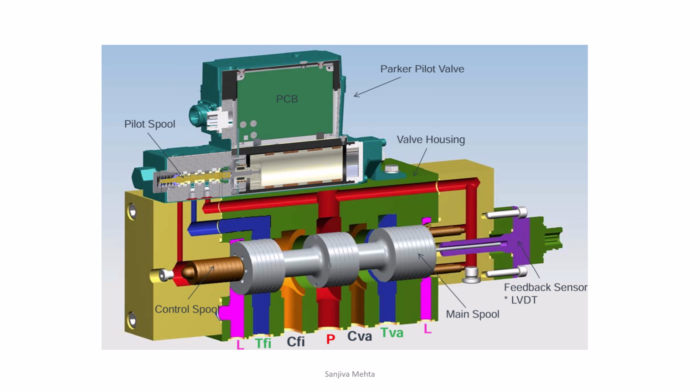This is your FIVA valve. These are various channels. This is the valve actuator. This is for the injection side. This is the valve actuating side, injection side. This is the pressure oil, and because this is moving up and down, up and down, and fast, it needs lubrication. This is the lubrication channel.